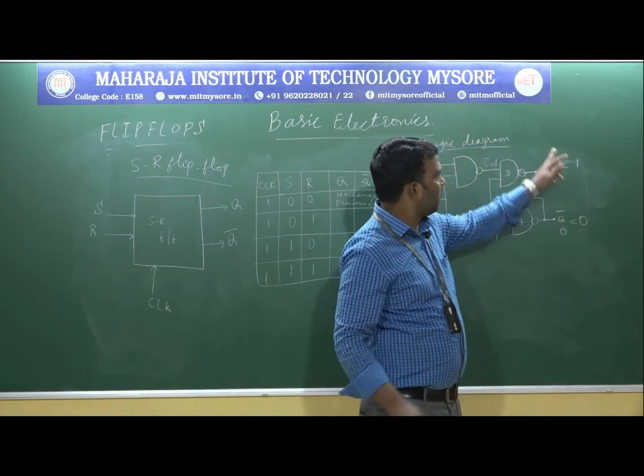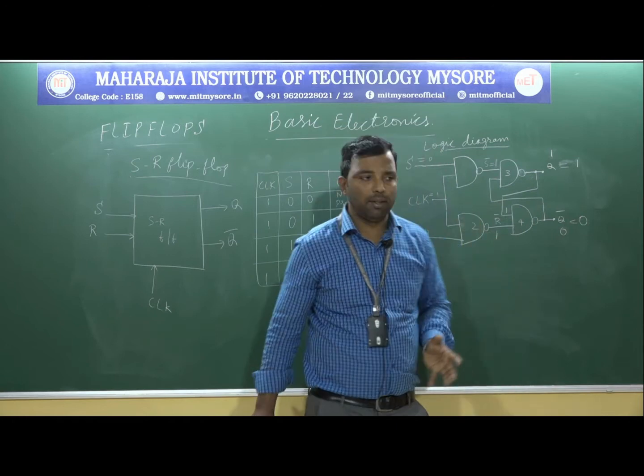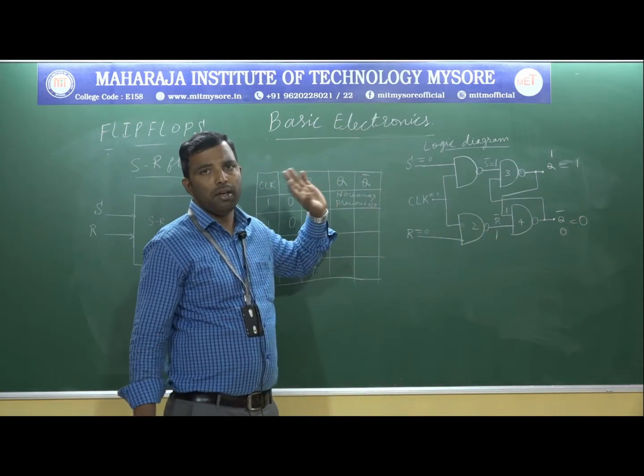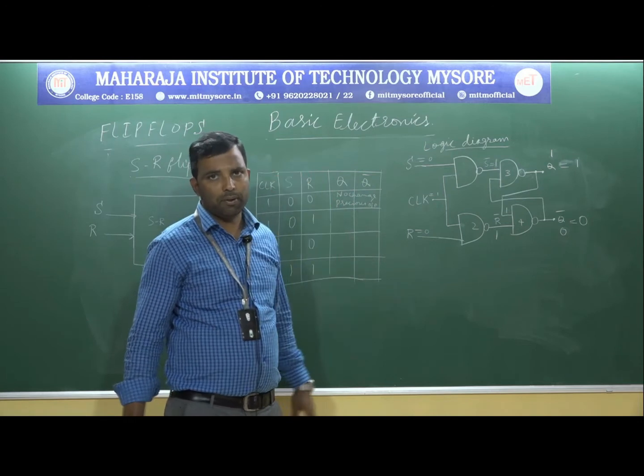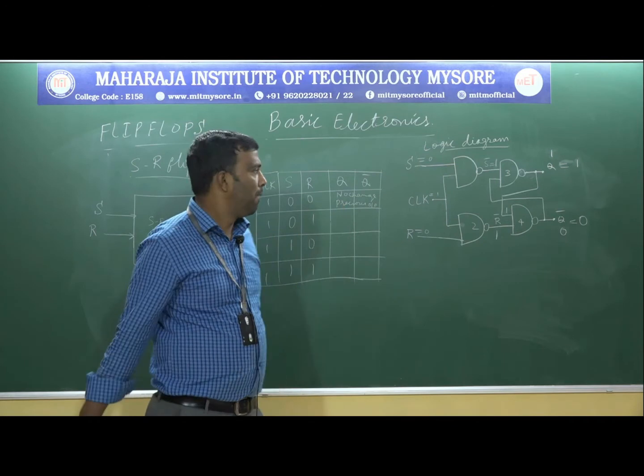Output for the NAND gate is 0. Observe here. The previous condition is 1 0. The present condition is 1 0. Therefore we can say that the output won't change. No change in the previous output. The output remains constant, same, won't change.